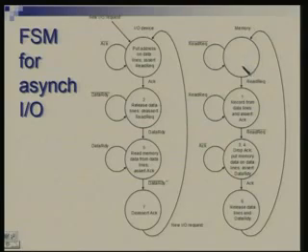When read request becomes 1, it comes to this state where it observes the data lines which are carrying the address, remembers the address, and asserts the acknowledgement line. On the other hand, after having done this, the device will be watching the acknowledgement signal. As long as the acknowledgement signal is 0, it remains in this state.